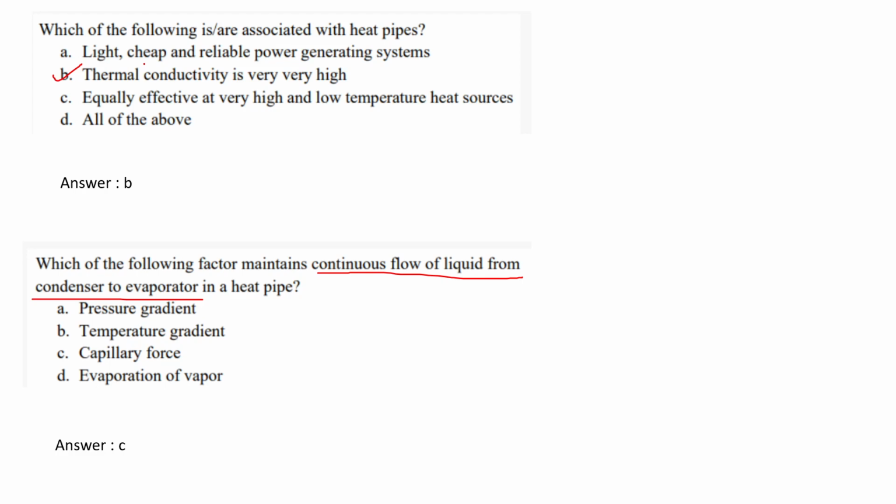this and all characteristics. Even a pump bearing can also be reduced in temperature. Even the pump bearing has an inside temperature. Correct, madam? You are asking about the limitations while the heat pipe is running. Yes, heat pipe application. We can develop much more on heat pipes. Right now, the de-icing of roads in some Western countries is one example. Similarly, bearing temperature for pump or on-demand bearing is there. That can also be reduced through a heat pipe.